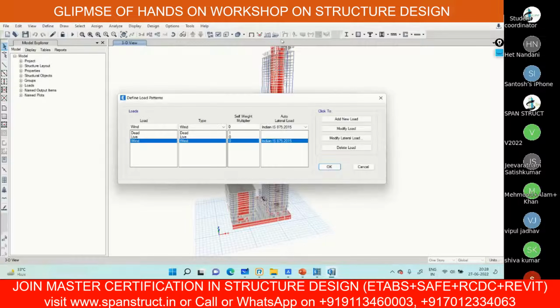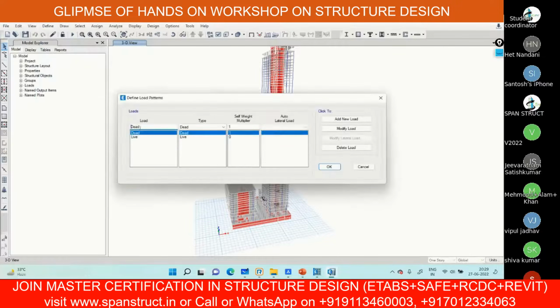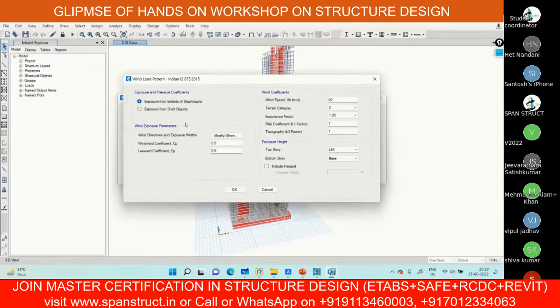Yes, sir. Please explain the wind again. Okay. So when you are going to apply the wind load here, I told you that you can apply through the automated lateral load also. When you go to the define option in the load pattern, define a wind pattern here, and select your auto lateral load code, that is IS 875 part 3 2015, when you add this, you may get an option of applying through the diaphragm extent and the shell object. So these two options you can select while applying the wind load. This is very automated. You have to give a few data here and automatically the wind load will get applied.